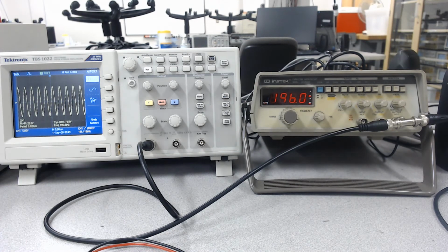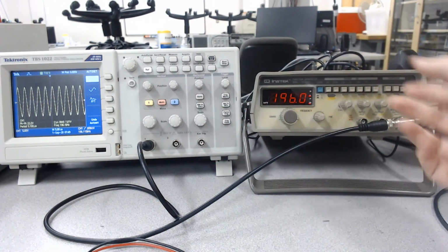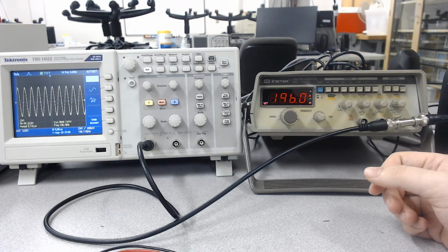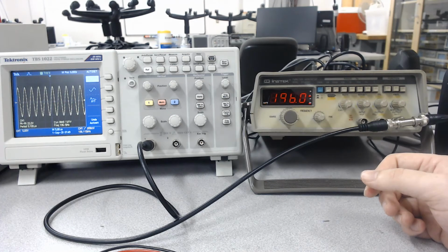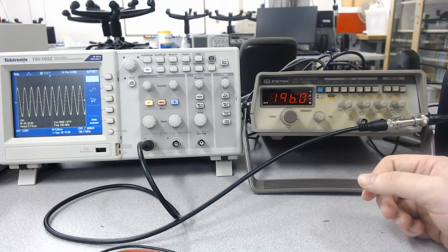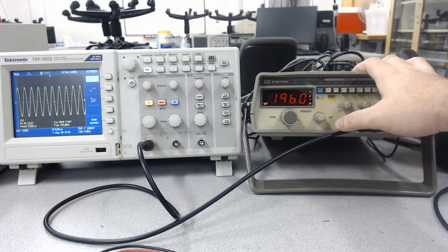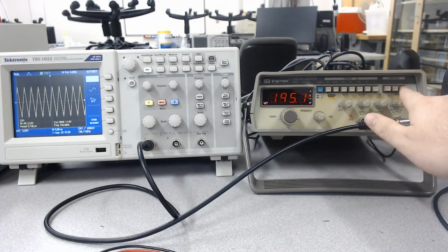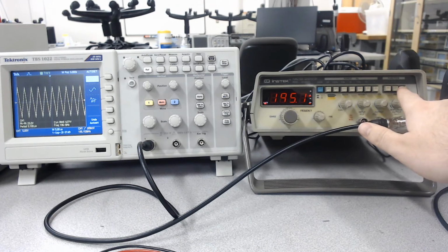All right, so now that we've been playing around with all of these knobs, what the Part 2 lab actually asks for is a sine wave of 100 hertz, a peak-to-peak voltage of 6 volts, and nearly zero DC offset. We also need to record the frequency displayed on the function generator. So the first thing we're going to do is adjust the sine wave. I'm not sure if I mentioned this before, but you can adjust the type of wave with these buttons up here. We want a sine wave, so we want the one that's smooth.